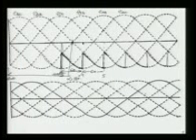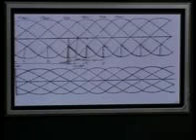It was going like this and like this. So it was 3, 2 and 1. You can also verify that this will be the output voltage, because 3 again 1, 2, 3, 4, 5, 6, 1, 2, again it is going to be in cyclic order. So this is your output DC voltage which is appearing across this in case of inverter mode, and we have taken alpha equal to 150 degree.